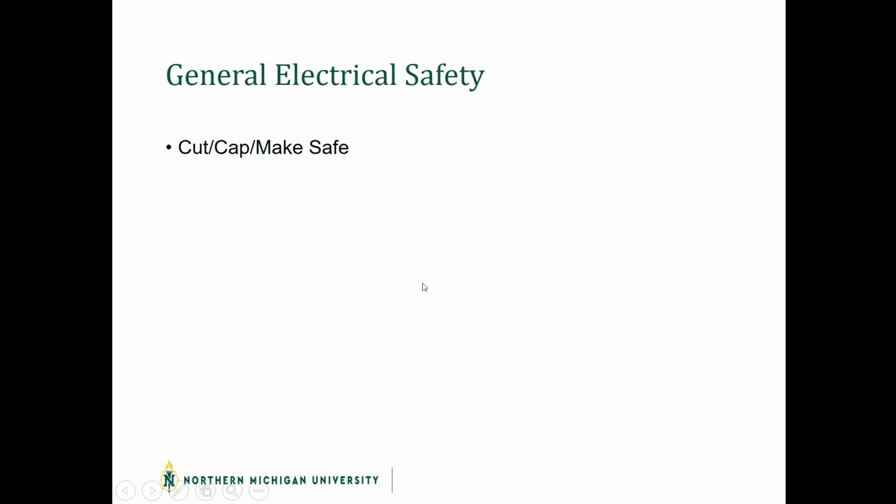Other things dealing with safety are scope writing and how we scope out different components when it comes to electricity. Cut, cap, make safe is always a big deal. It's for all of your MEPs, because your MEP trades are the only ones certified to go in and de-energize your electrical circuits. Mechanical are the only ones that can disconnect all of the ductwork or whatever else they need to do. They need to coordinate with electrical to make sure we don't have any kind of automation within there. Same thing with plumbing. You want to make sure the pipes are cleared and dried in that location before we cut. So: cut, cap, make safe.